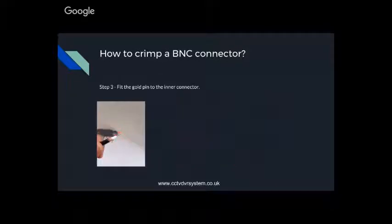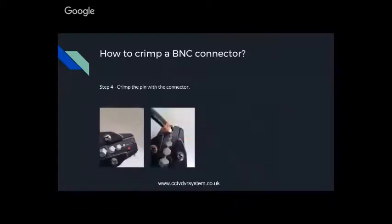Then put the pin. And once you put the pin, you need to crimp the pin. That's very important. So when you buy your BNC crimp, make sure it has the correct crimping tool to crimp the pin. Let me show you. This one, you see that smaller one, that can crimp the pin. So once the pin is inserted into the copper, you just crimp it.